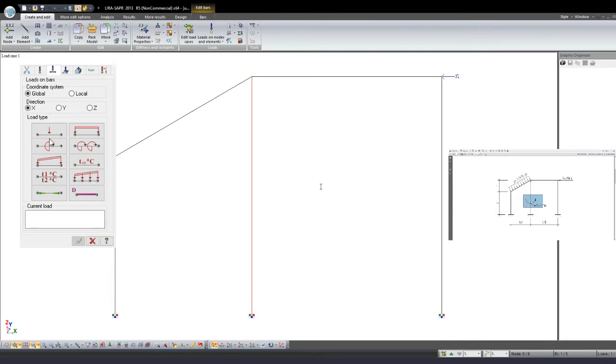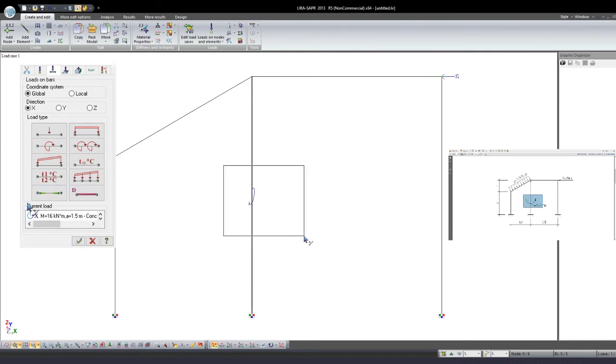Okay, after this, A, you can see A is from the first node to the second. When I create this bar, the first node will be here, the second here. It means A starts here. Okay, I write how many. The whole length is 3. I write 1.5. Touch apply. Oh, I am sorry, I made a mistake.